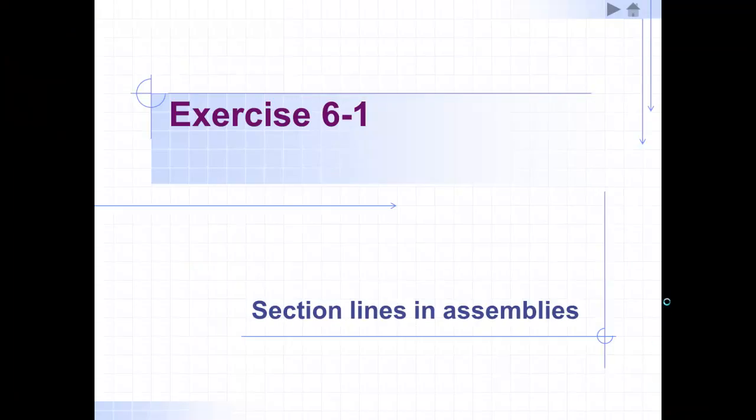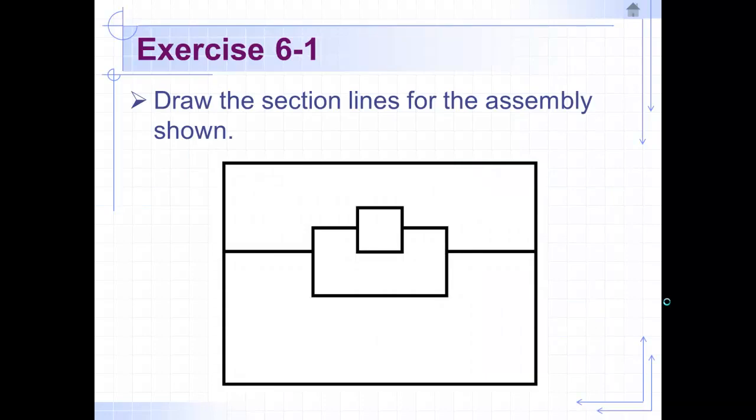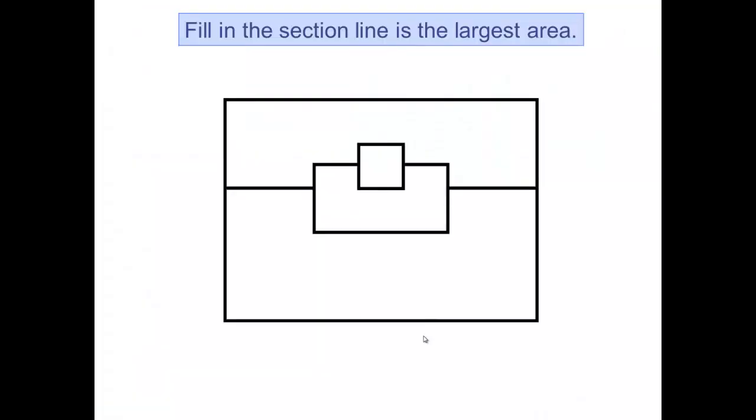The reason for that is an assembly is composed of many parts. So instead of just going with slanted lines, just like when we did the crosshatch for a part, we actually have to follow it based on every single part. So these are 4 different parts that are connected together through an assembly, and we went ahead and created a section. That's why when we create the crosshatch, we have to start with a sequence.